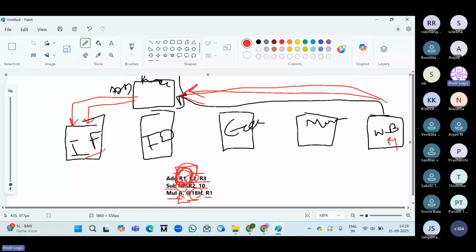So here, after fetching the instruction from the memory, usually from cache, we will have all these instructions in the cache only. And these data will go to the decode stage. These instructions will be decoded, and the control signals are generated. Also register operands will be read here. For add, it has some binary data, and that binary data will be decoded here, and the registers have some binary data, and that data will be decoded here.